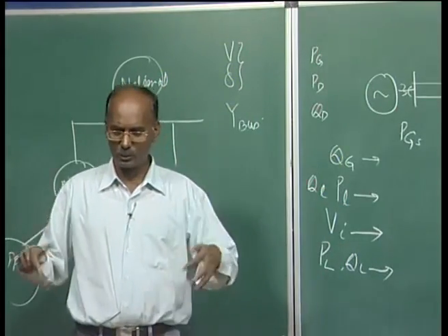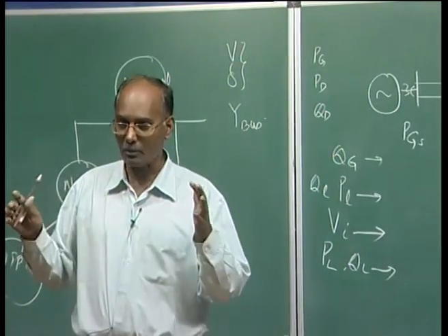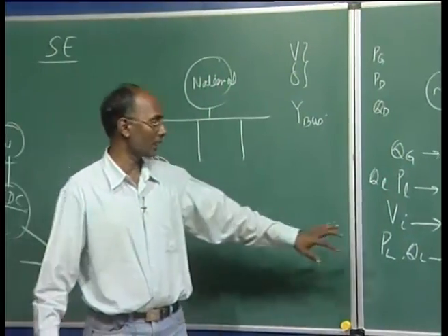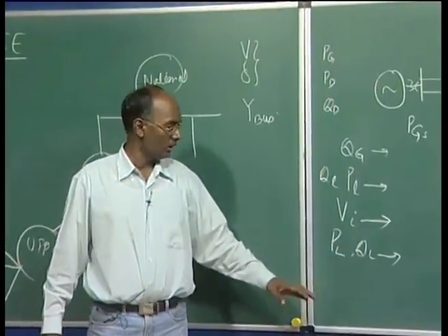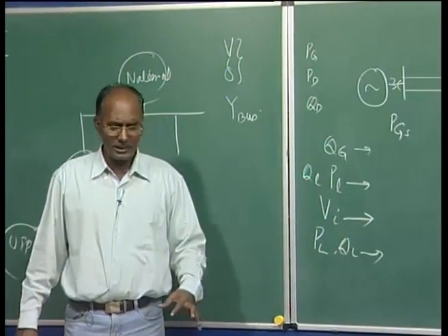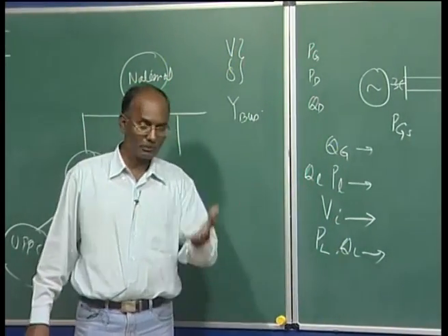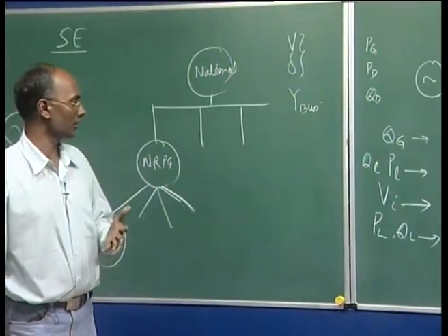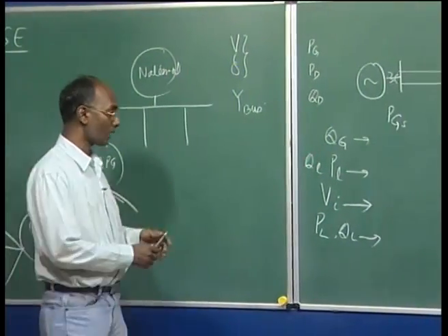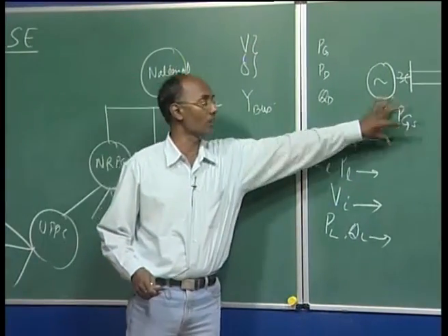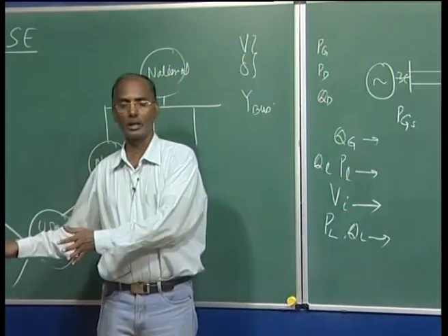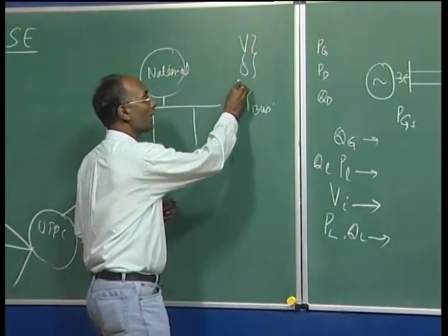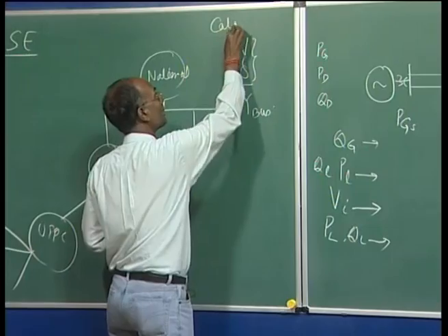We can get, again, we should design especially that is required in the planning stage. We want to minimize the losses, we want to design our system so that it gives minimum loss. In the operating state also, by changing the reactive power injection we can minimize the losses, and that can also be done online. We can also go for the cost minimization based on the scheduling of the generators, again online and using your load flow.